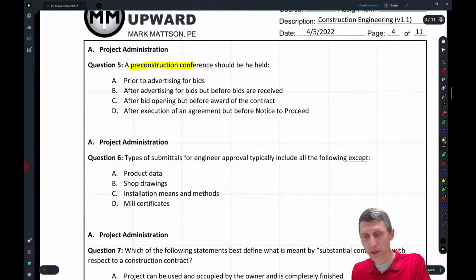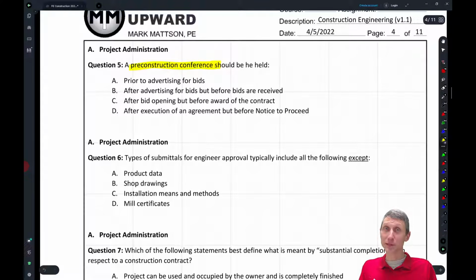And I've gone to a bunch of meetings in my life for different jobs, but specifically a pre-construction conference. So what's a pre-construction conference? It's a conference between parties before construction, right? Nothing too crazy. You're going to talk about site access. You're going to talk about working hours. You're going to talk about points of contact. You're going to talk about safety precautions. You're going to talk about traffic schedules, different things along those lines, staging, some of those things, right?